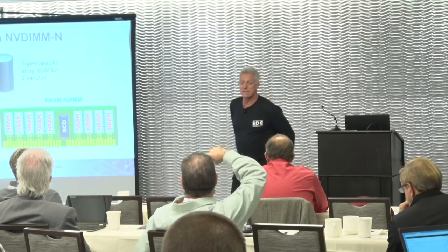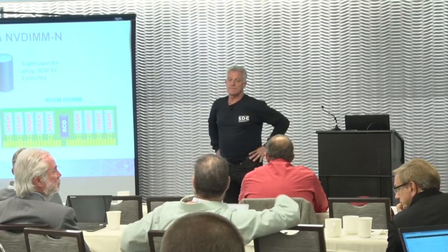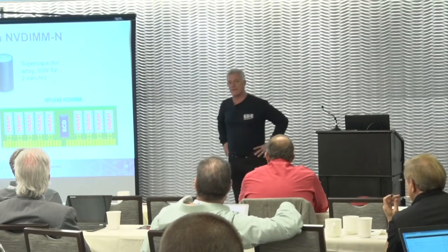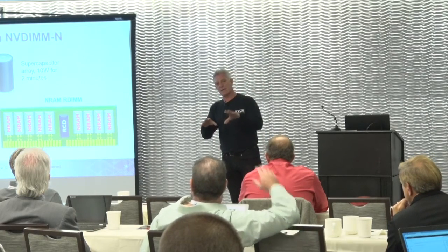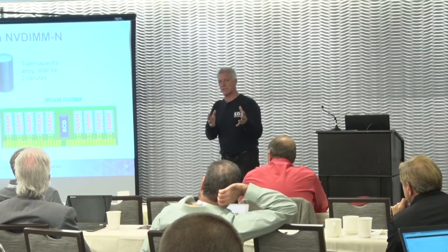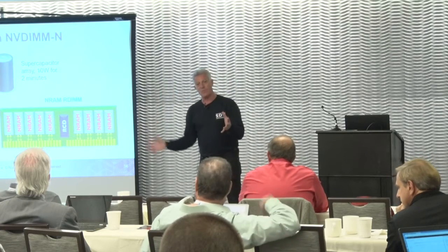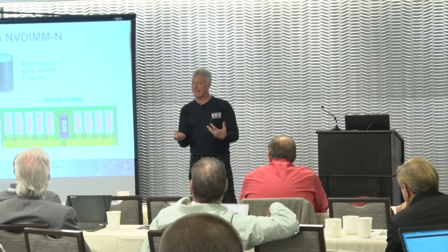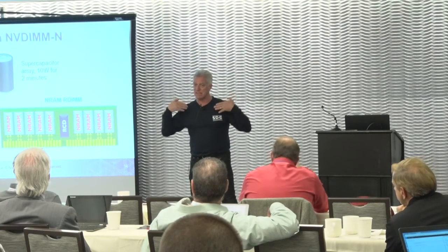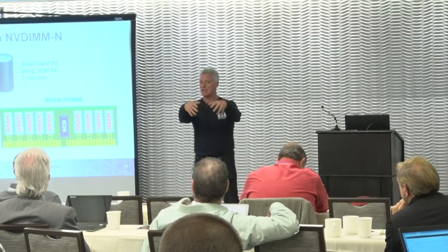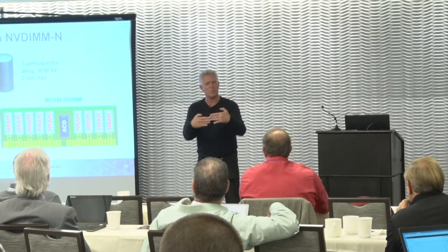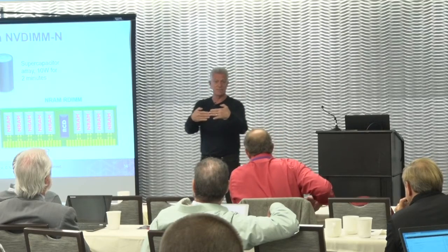What about power glitches? Yeah, the power glitches would affect it the same way anybody else would be affected, in the sense that, what happens if you have a power glitch today? Hopefully your CPU detected it. If your CPU detected it, what the CPU does is it completes the burst that's in process, puts the memory in self-refresh, and that's kind of the trigger point for NVDIMM-N today.